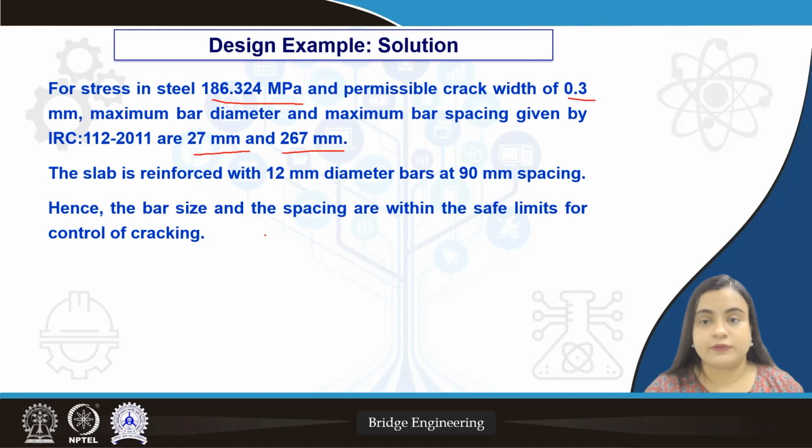Here we have reinforced the slab with 12 millimeter diameter bars at 90 millimeter spacing. So the bar size and the spacings are within the permissible limits of control of cracking.